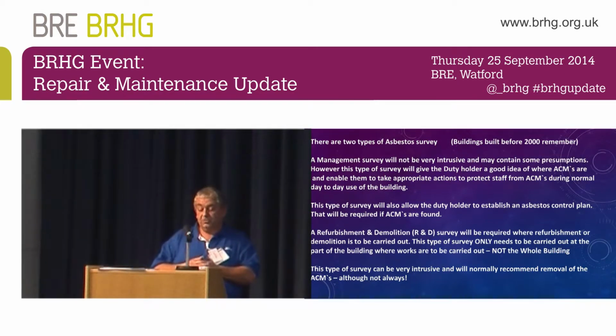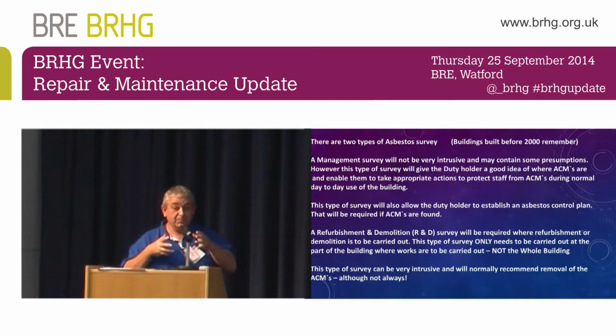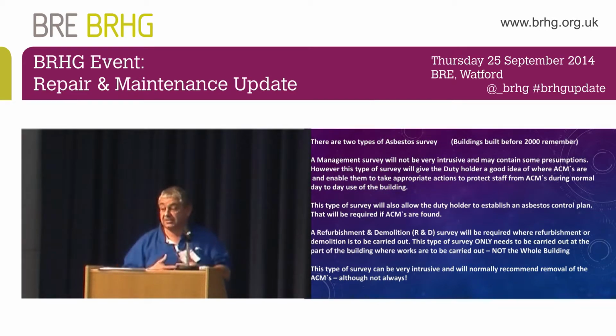It will give the duty holder a good idea where asbestos-containing materials are, and enable them to take appropriate actions to protect staff from the asbestos-containing materials during normal day-to-day use of the building. This type of survey will also allow the duty holder to establish an asbestos control plan. It's something also that is a requirement. You need a control plan.